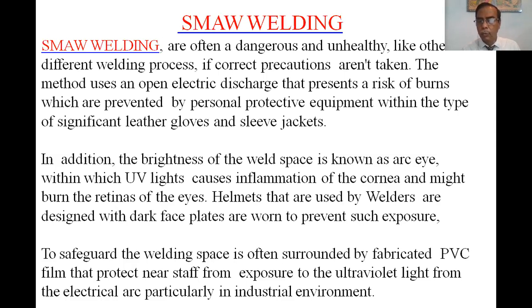Helmets used by welders are designed with dark face plates to prevent such exposure. To safeguard others, the welding area is often surrounded by translucent PVC film that protects nearby staff from exposure to the ultraviolet light from the electric arc.